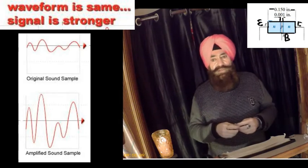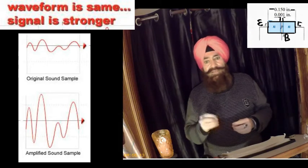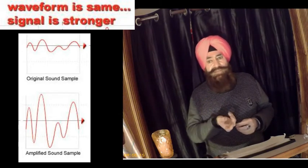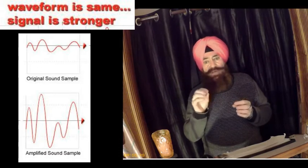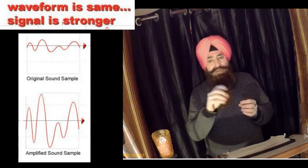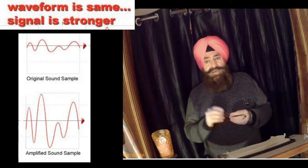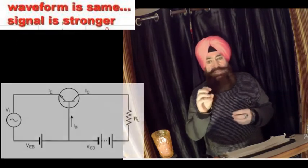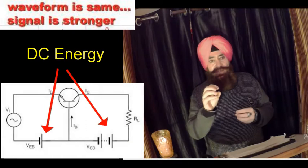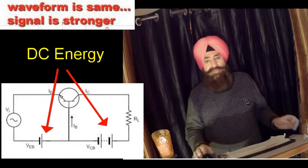Too often it is assumed that the transistor is a magical device that can raise the level of the applied AC input signal without the assistance of an external energy source, but that is wrong. The transistor amplifies the signal at the cost of the DC energy levels applied at the emitter, base and collector.